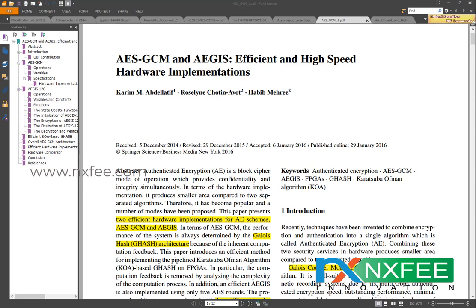To address this limitation, this work proposes a high-speed AES-GCM authenticated encryption architecture using a 128-bit overlap-free Karatsuba GF multiplication technique together with a parallel KOA GHASH controller for efficient authenticated processing. The proposed architecture also integrates a carry lookahead adder to reduce arithmetic propagation delay in both the AES and multiplier data paths.